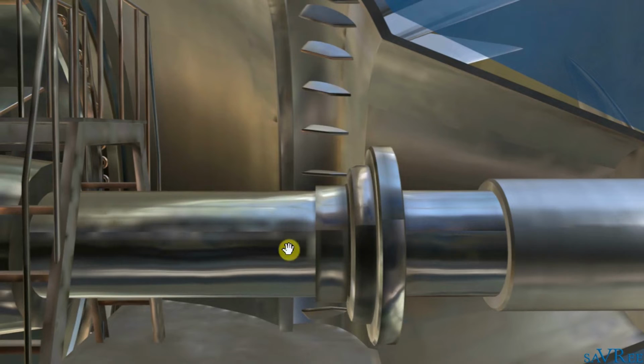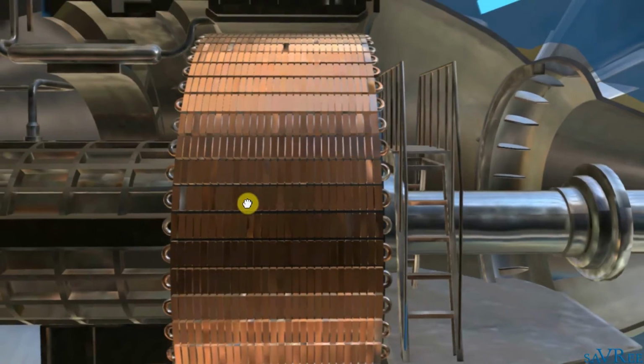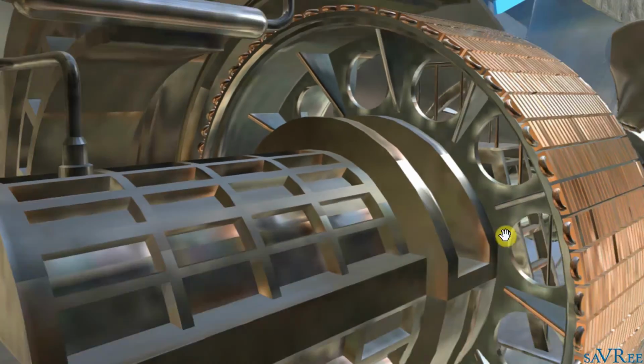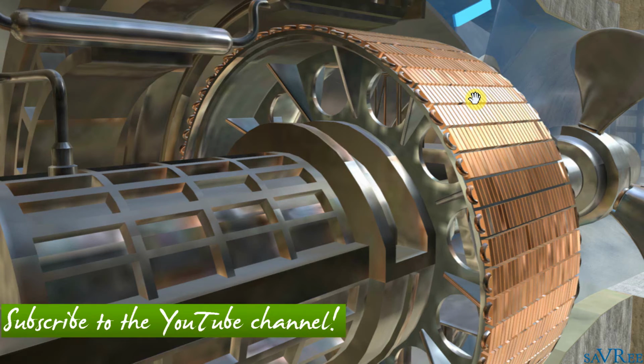The propeller is connected on a common shaft to a rotor. As the propeller rotates, it rotates the generator rotor. That is this component here. And as the generator rotor rotates, it induces current in the generator stator, and when we induce current in the generator stator, we get current flow, and at this point we are generating electricity.